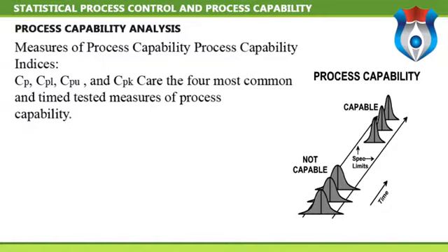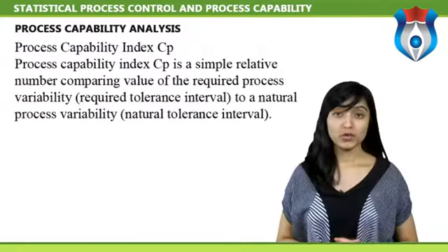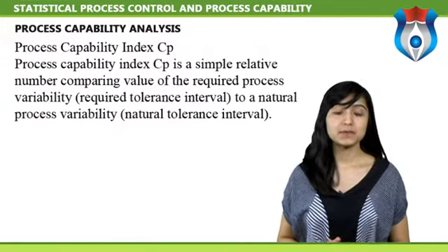They can be used effectively to summarize process capability information in a convenient unitless system. CP and CPK are quantitative expressions that express the variability of a process, its natural limits relative to its specification limits, the customer requirements.